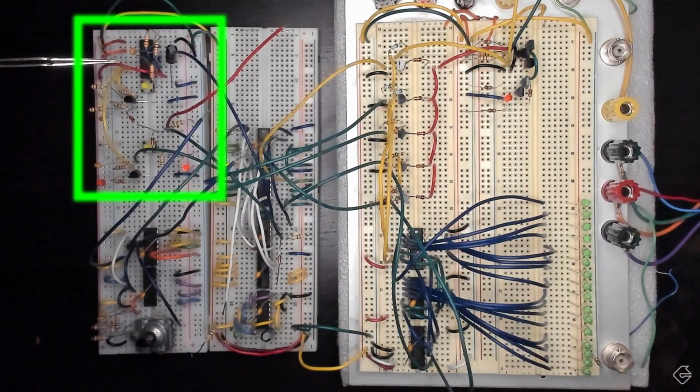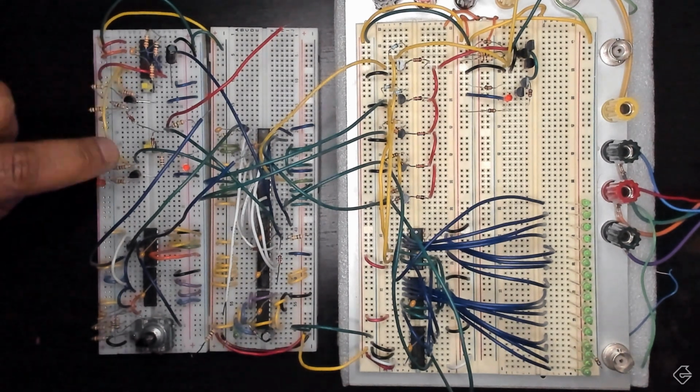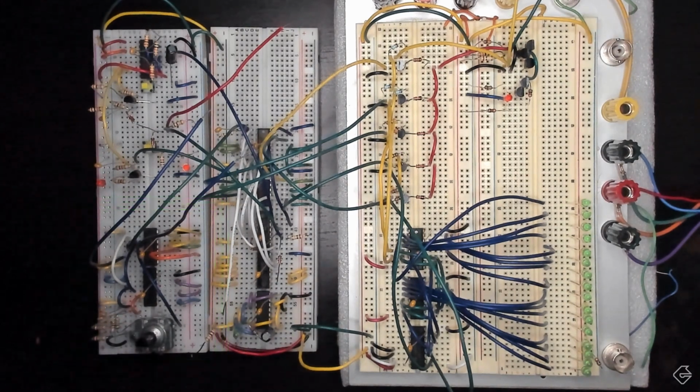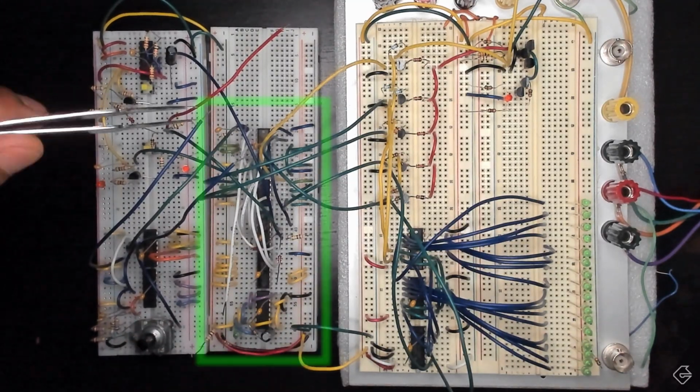This portion in the top left over here is basically a clock generator portion, but it also has two buttons. And those two buttons allow us to turn the intensity of the LEDs higher or lower. Down here, we have an alternative user interface. This uses a rotary encoder, or a dial, that I can turn so that the intensity of the LEDs goes higher or lower. On the middle breadboard is all of our logic that we needed so that the LED intensity doesn't go beyond the maximum or below the minimum, and it has all sorts of stuff to make sure that it can increment at a comfortable pace.